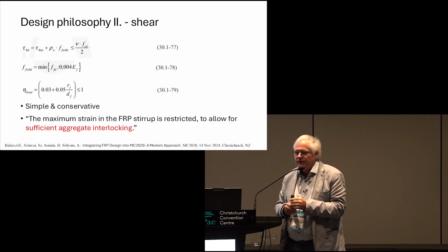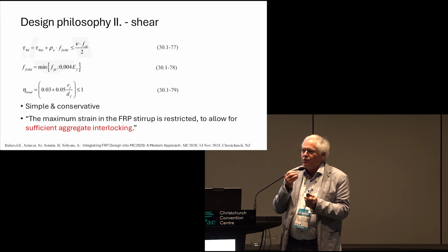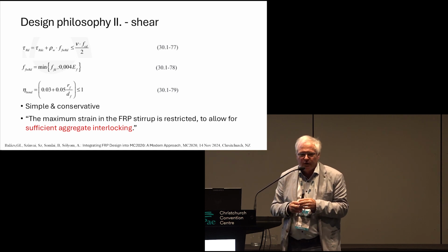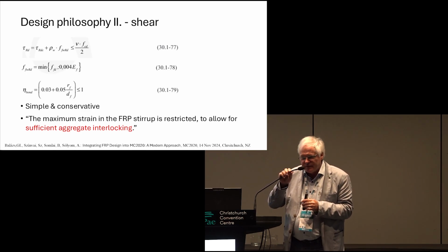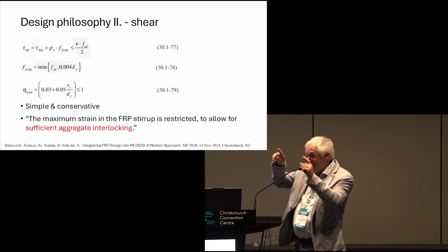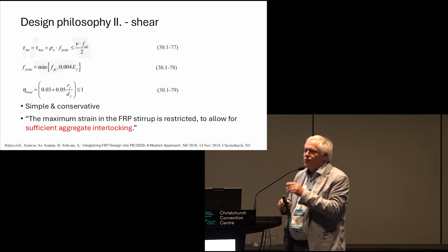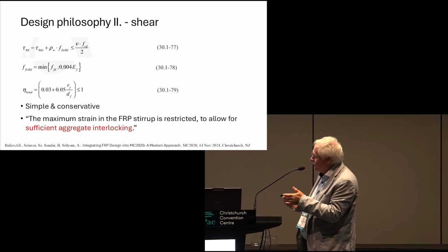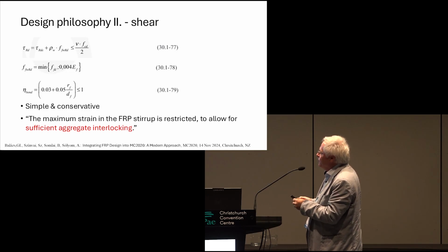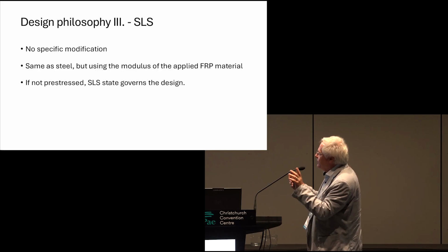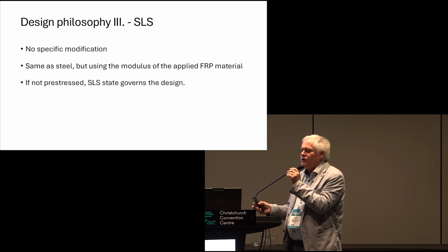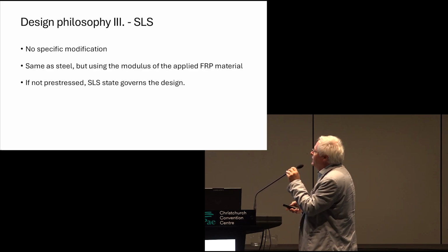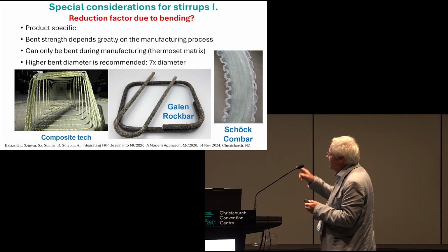If you go into details, the proposal in many papers, literature and codes as well, is to apply about a 0.7 reduction for any bend, even any stirrups. You can use this, and you can live with that, but we can go into some details briefly. It is very important not to forget about that. Yes, okay. This is what I wanted to mention.